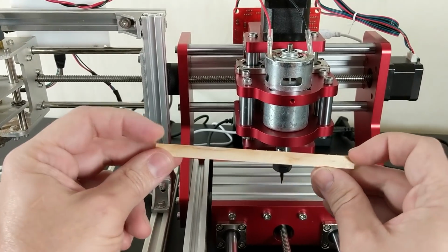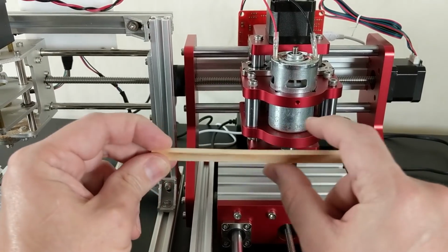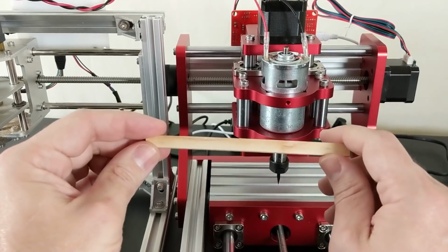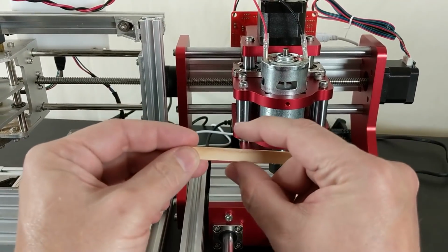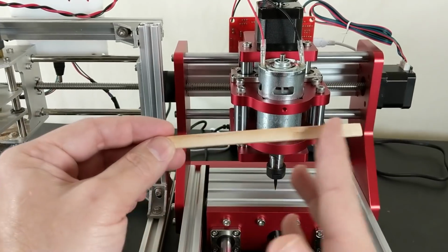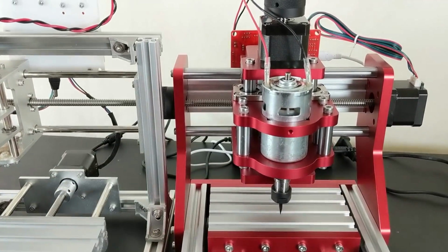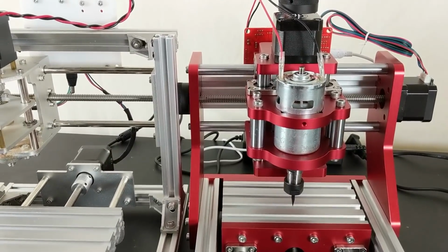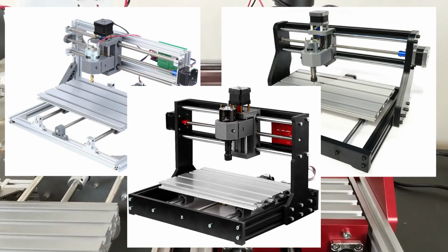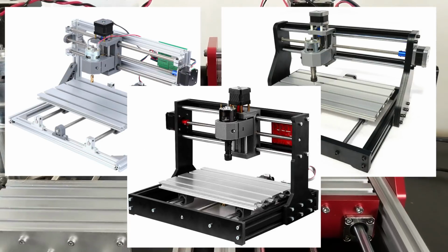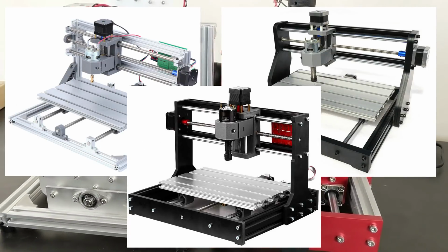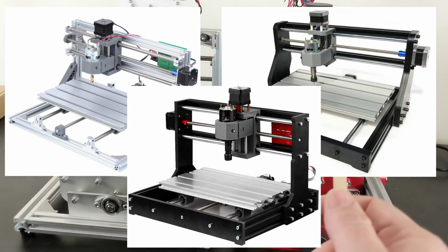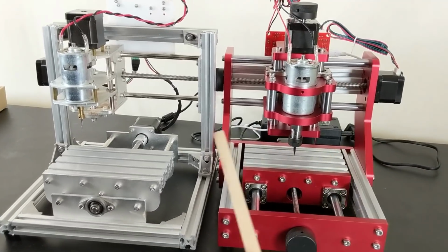And if I flip this on its side, now this is twice as thick as that, and I apply that same amount of force that you just saw me applying, I can't bend that stick at all. So we have a number of things at play here. First of all, the thickness of the member, also the total length of the member. Now, that's key, the length, because look at all these other machines that I'll flash on the screen. These are your under $500 CNC machines available from China. And as you can see, every one of those machines is larger than these two machines, which means that it's just going to be less stiff based on the length.